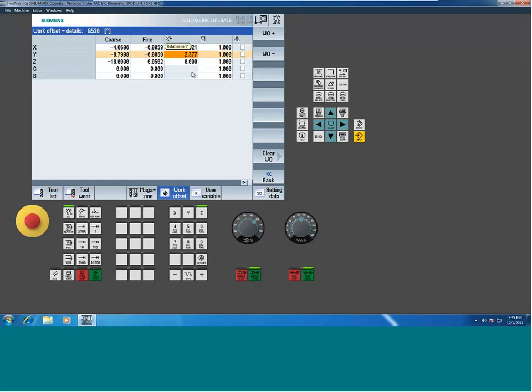And this always writes to the coordinate rotation, right? So it said, hey, based on those 3 points and the plane I just created, it means that to make the spindle normal to that surface, I would need to rotate about my X 19.4 and about my Y 2. And these can be plus or minus values. It all depends on the 3 random locations. So she now knows a surface.